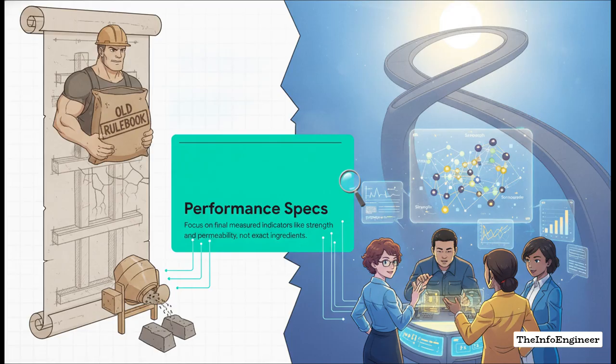But performance specifications, which is what governs design mixes, they don't lock you into specific ingredients. Instead, they focus entirely on the final measured indicators, things like compressive strength, shrinkage, chloride permeability. Performance specs actually give engineers the freedom to innovate and really optimize the mix for whatever the specific structural needs are.